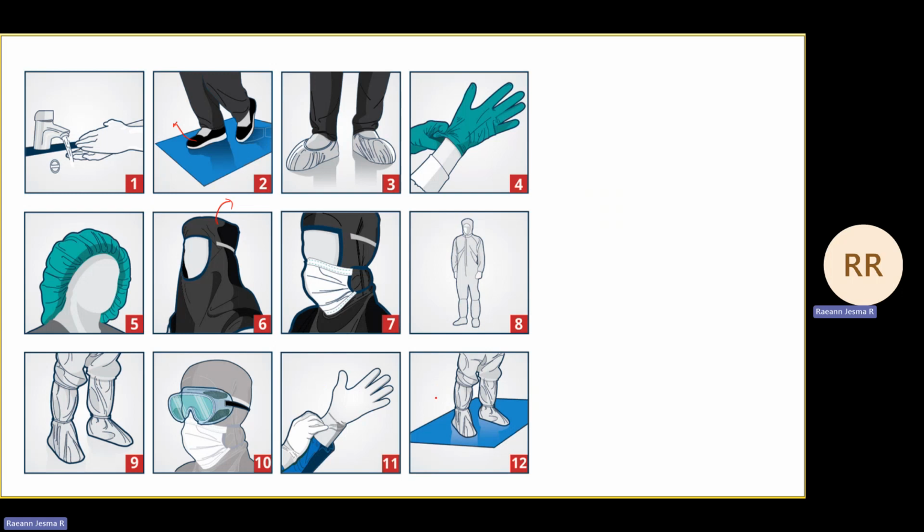So before you enter your clean room, you again stand on a sticky mat in order to remove any particles that may be present below your shoes, the clean room shoes. Is this clear?